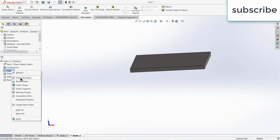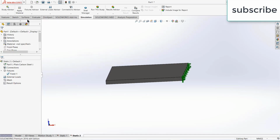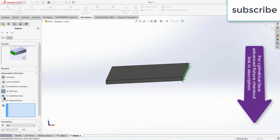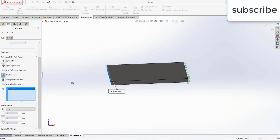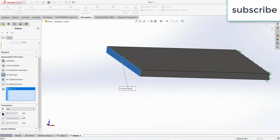Now right click on fixtures, click on fixed geometry, select this face, click OK. So go to fixture advisors, click on advanced fixtures. In this video, I'm just going to talk about flat faces. If anybody wants to learn about cylindrical faces, you can check out the previous videos, link in description. Okay. So the first thing we need to do is select a flat face. Now suppose somebody wants to select a curved surface, then you need to select cylindrical faces. For flat faces, basically we use this.